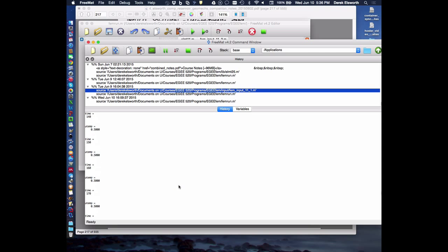we go back to the first time step. Yeah, okay. So it's going up from 0 to 0.5, so it's at 0.45, then it's at 0.4959, 0.4996, and then 0.5. And so it is. So the difference between conditionally stable and unconditionally stable systems is that if you choose the wrong time step, then you get a stupid result, an oscillating result which just goes unstable. At least with an unconditionally stable system, we could probably use as big a time step as we wanted.